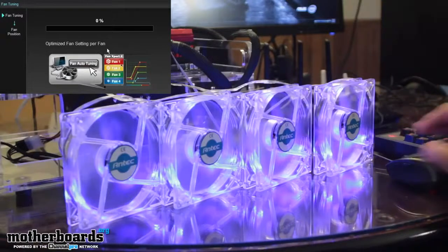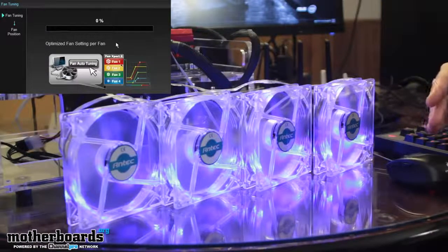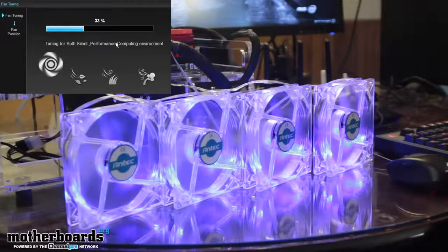All right. So at this point, we can see that the actual fans have all now ramped to 100%. So these are the 6 fans that we have connected. We have 2 on the CPU and the CPU optional header, and then the chassis headers 1 through 4, we have the 4 other fans that are connected. Now at this time, it's gone ahead and maxed them out to their max RPM value, and it's incrementally slowly bringing them down to lower and lower and lower RPM values. And all this data is being cataloged.